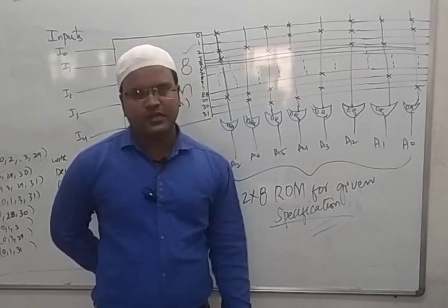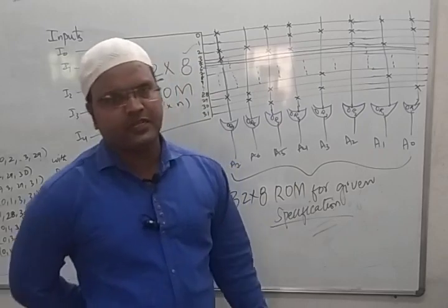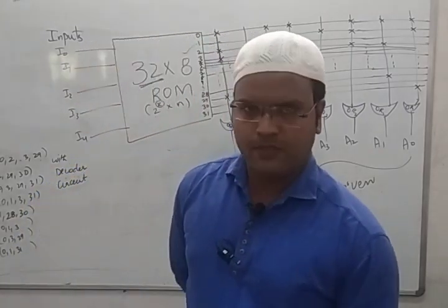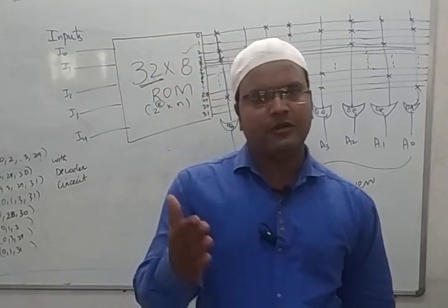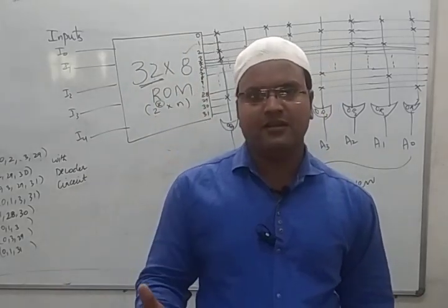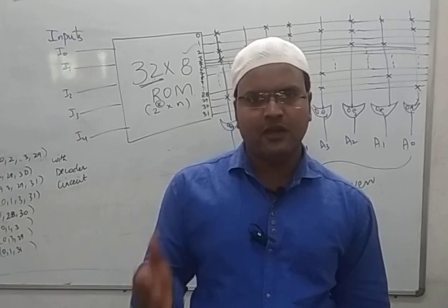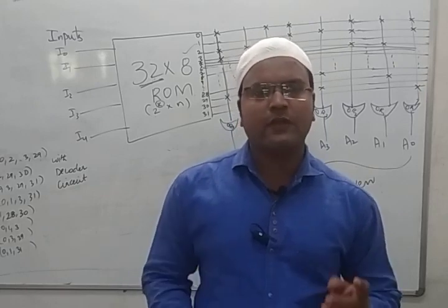So next we will see PLDs. PLDs are of how many types? There are 3 types in that. One is this, ROM. Next is PLA, that is programmable logic array. Next is PAL, programmable array logic. How do we design? We will consider only 2 types of gates.